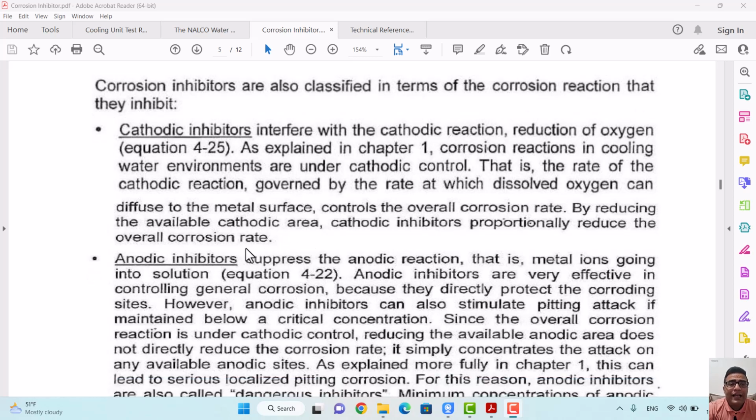So, this paragraph states an important sentence here. It says that the main corrosion in cooling water piping stems from cathodic reactions. So if we try to reduce the cathodic sites by adding corrosion inhibitors, we can dramatically reduce and control cathodic corrosion, and as a result, overall corrosion.